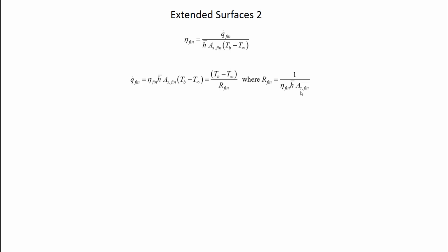It's related to the other resistance that sits inside of this solution that impedes heat transfer as you have to move it along the fin to have it be convected. If the fin efficiency is 100%, then I limit back down to just being a convection resistance, which is exactly what that ideal fin is. But as the fin efficiency drops, I have more resistance than I would get if I were just including convection resistance.